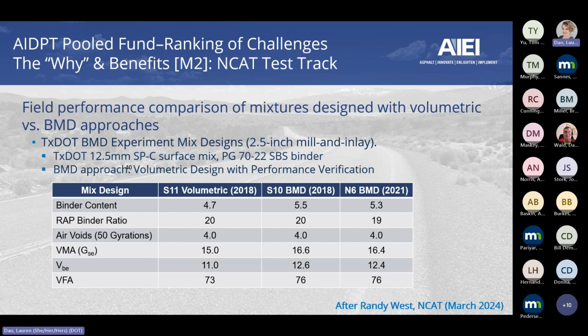Which means that while you're adjusting the asphalt binder, you must be doing some adjustment to the gradations. And this is another thing that we learned throughout those workshops and talking to the different agencies and contractors, that gradation now also plays a major role. You can make adjustments to your gradations to meet your balanced mix design.